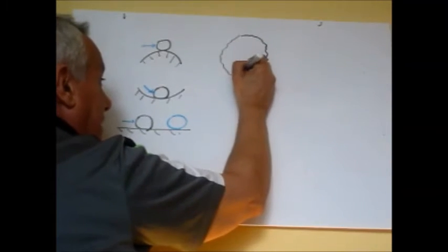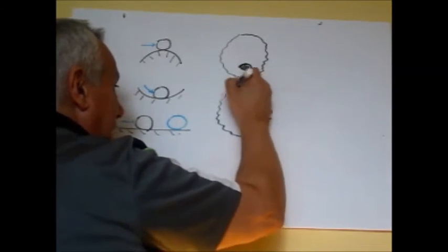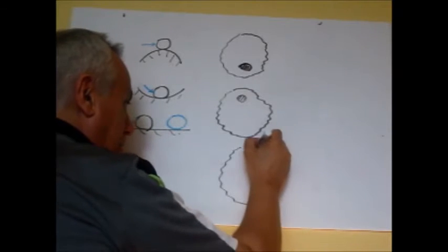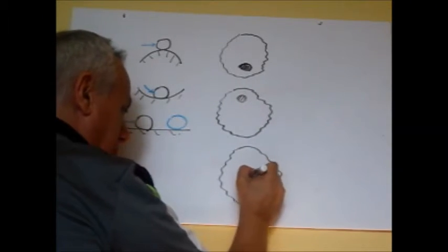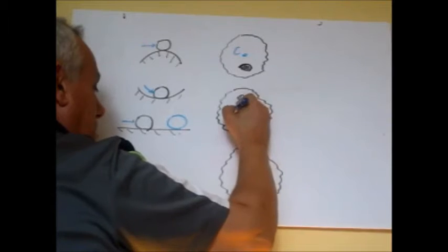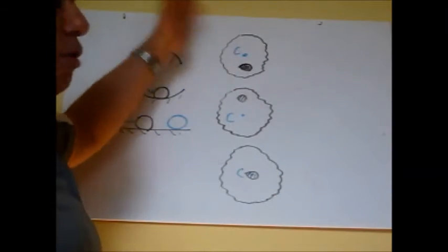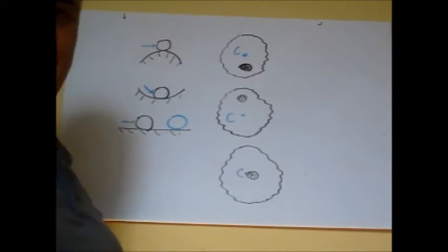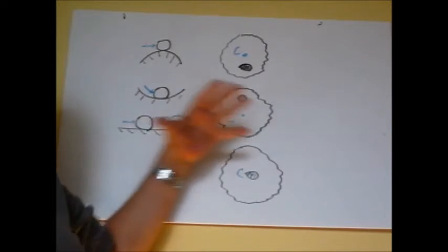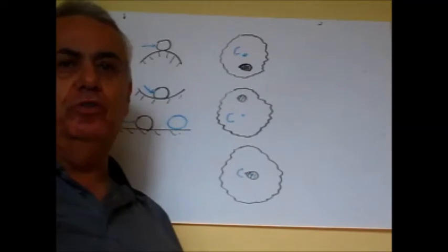In many other books, you have seen this concept with a body rotating about an axle. This is the axle of rotation. You see, it's the same body. Now this is the axle of rotation, and it's the same ugly body, a potato, with this axle of rotation. This is the centroid, the center of gravity of this body, this one, and this one. So now the first one, if I push a little bit, is going to leave this equilibrium and never come back again: unstable equilibrium. This one is going to shake, but come back again: stable equilibrium. And this one is going to rotate and go to another position of equilibrium: indifferent or neutral equilibrium.